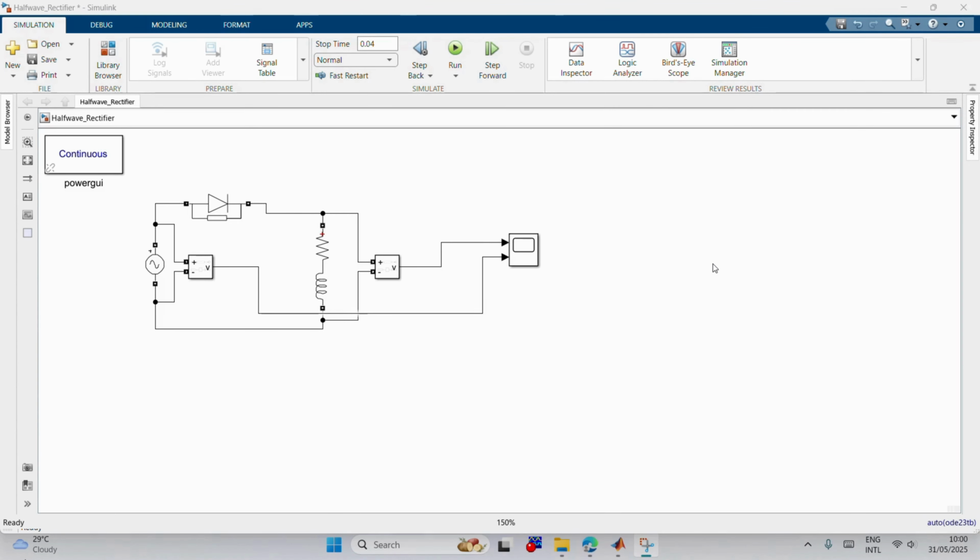The next transformation is time reversal. In time reversal, we can't actually show it in the oscilloscope because the scope only reads a real-time signal, meaning it can't show us the negative time because there is no such negative time. If we wanted to visualize the time reversal of the half-wave rectified signal, we're just going to flip the original signal to the left.